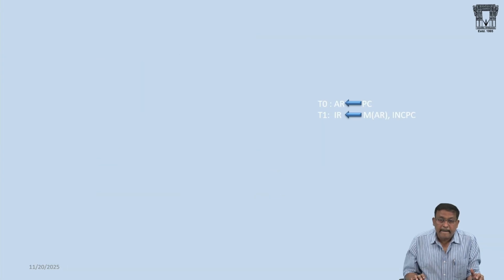Look at this one. Now I am trying to execute the machine instruction. During the clock pulse T0, when the clock makes a positive transition, the contents of PC are transferred to the address register. And subsequently, in the next clock pulse T1, when the clock makes a positive transition, two micro operations are performed.